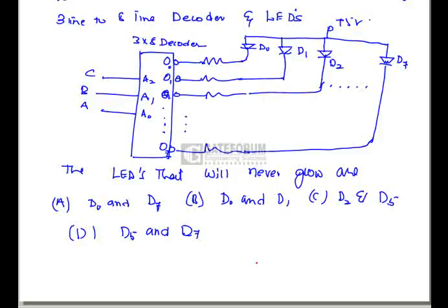The ABC will never get those values as outputs. So if we give that to the 3 to 8 line decoder, there are 2 lines that are not going to be activated. The inverted bubble indicates active low. In normal position O0 is 1.